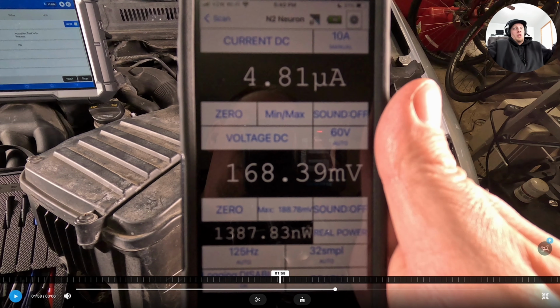So you're asking, is this good or bad? I don't know, if you're not familiar with what is a normal or acceptable voltage drop. The industry standard, if you look at any engineering documentation, is usually between 2 to 3% voltage drop. There are a number of online calculators you can use to determine how to calculate this, but in effect, 168 millivolts is acceptable. There's no problem here on this circuit. This is completely normal, just as a cliff notes.